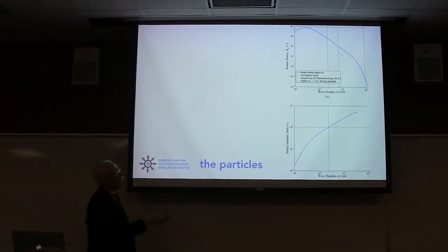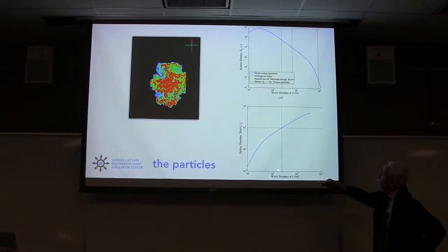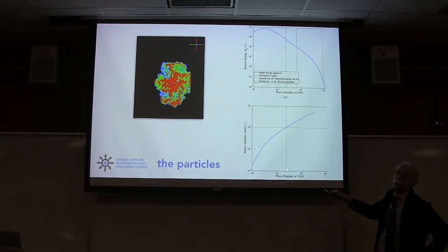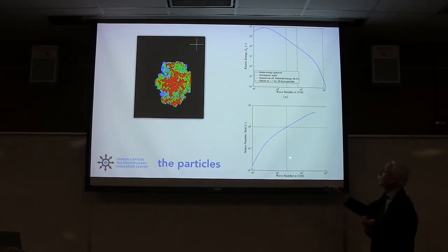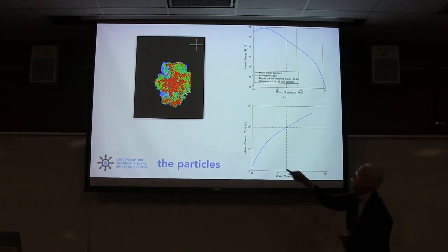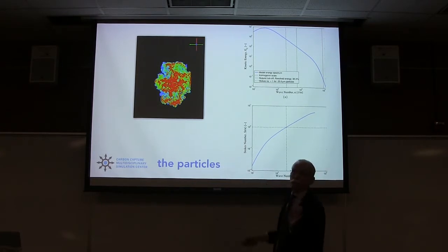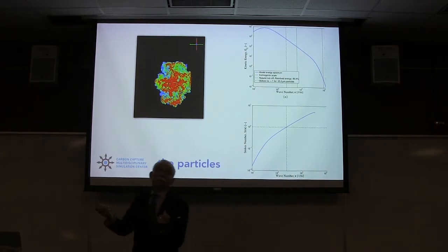Now, if we go to smaller particles, so here's 25 micron particles. There's its mapping of its wave number, its eddy size, to its Stokes number. It's sitting with a Stokes number of 1, and we're still resolving all of that. We're resolving everything to the left here. And there, at the very same time slice, is where the small particles are. So the last one showed you where the large ones are. So you get this segregation process.